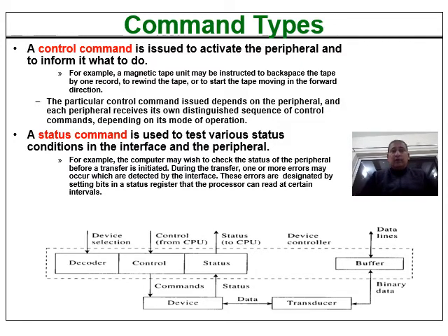As you can see from the direction of the arrows, the control command is coming from the CPU and going into the device, which is used for activating the device. Whereas this status information is going from the device to the status register, and from there it goes to the CPU. The status information is going from the device to the CPU, right?